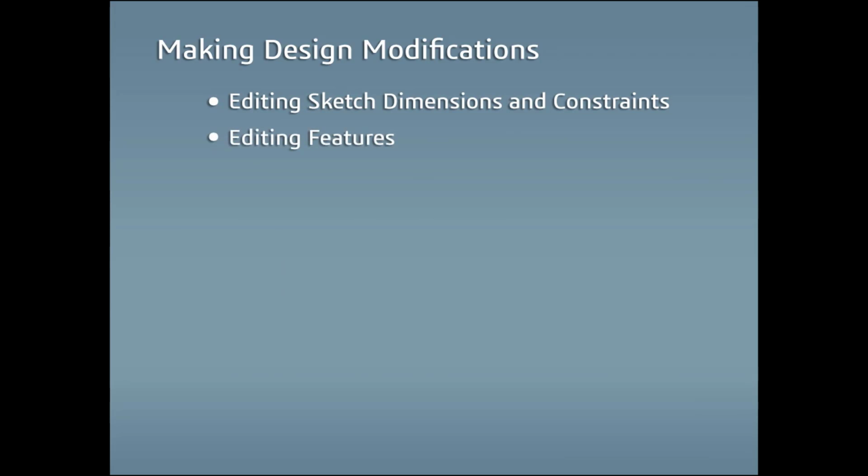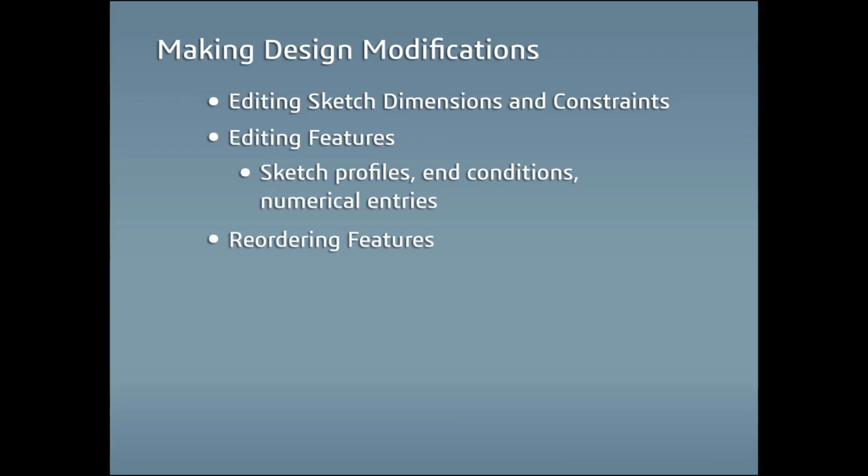editing the features themselves to incorporate different sketch profiles, end conditions, and numerical entries, and by reordering features in the Design Manager and using the rollback functionality to add new features at certain points in the design.